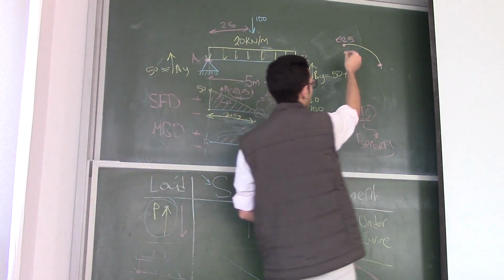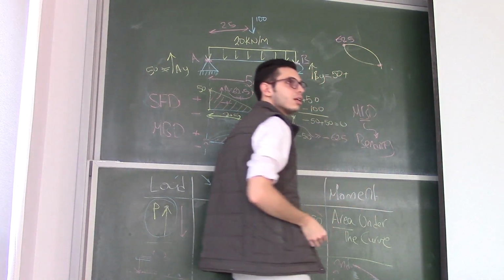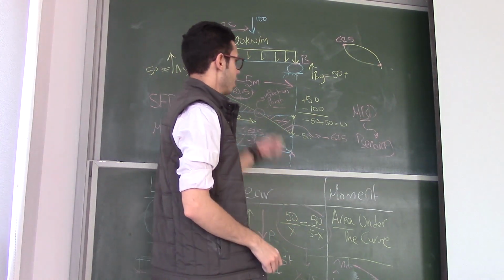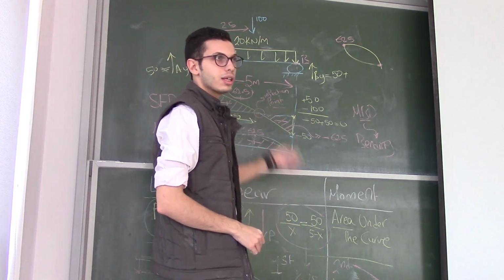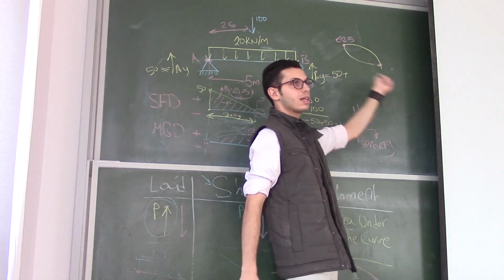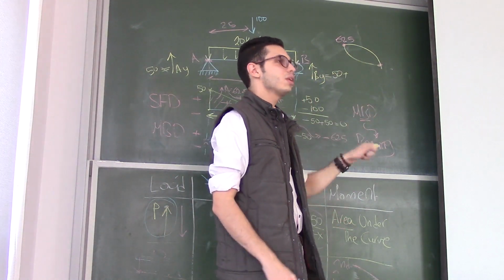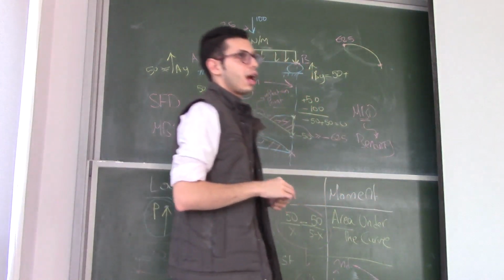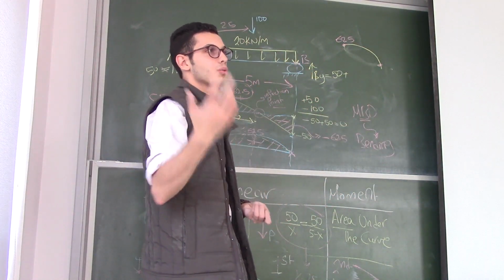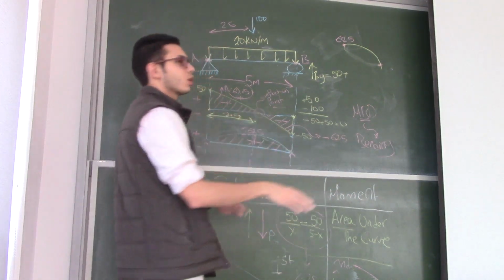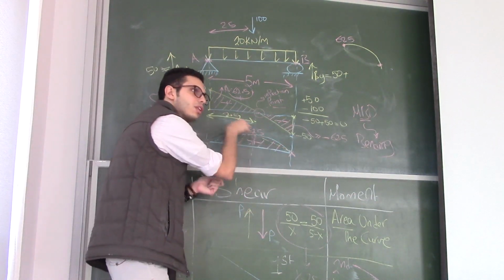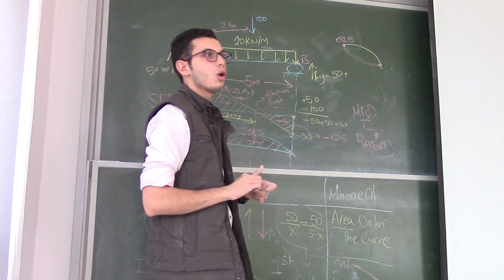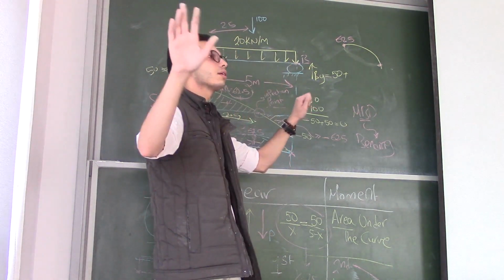Okay, you were asking why not like this. You should know about the integration. It's a negative slope, and you will get a negative, so it's not going to be like this. It should be like this. It depends on mathematics. Since you do not have a good background in integration, just follow this rule: imagine there is a line between these two points, and draw the curve up of the line, always up of the line. Is that clear?